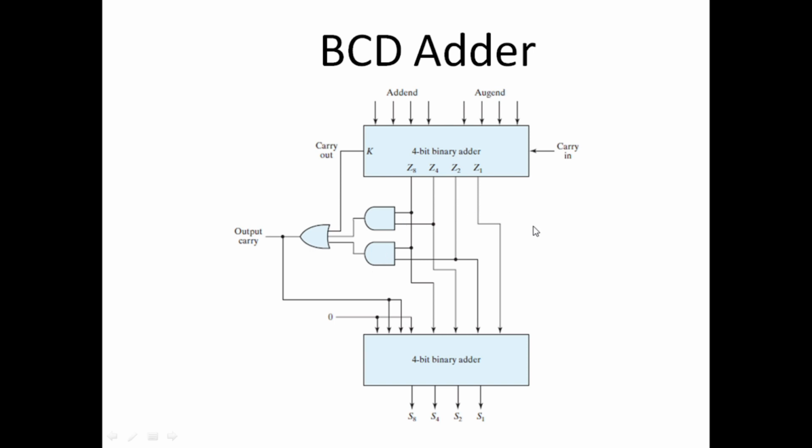So we implemented a BCD adder using 2 MSI chips and 1 SSI chip. The final output carry is not shown again here, but its value is always equal to this output carry, so it is not required to show it again because it has already been shown here.